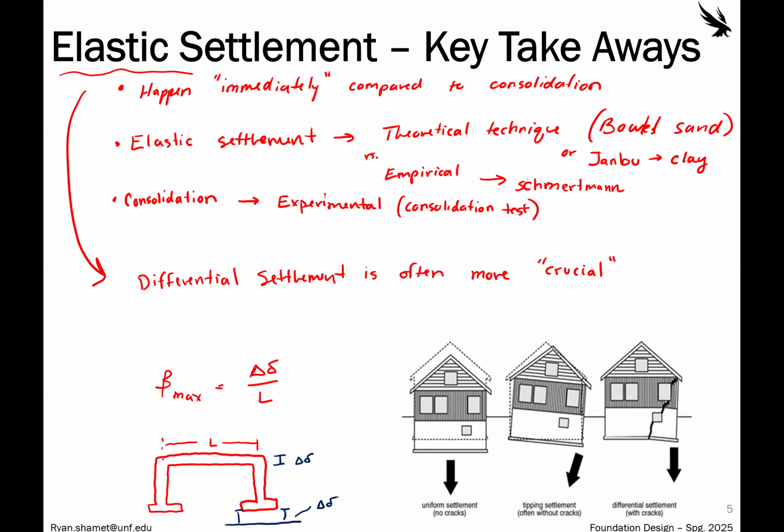So that's the net change in deformation. And you can look up the many different accepted codes for this, based off of the material type. Plaster, for example, will be able to achieve a certain amount of differential settlement. And it's all shown in these functions, delta by length. So it's like a slope rather than just a set settlement.